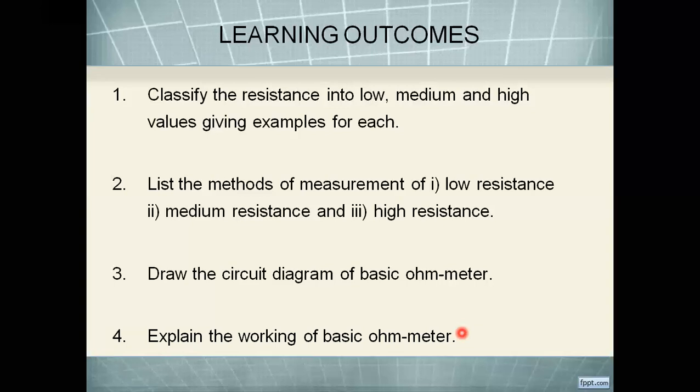We don't have a special meter with different working principles used here for a basic ohm meter. Let us recollect that we just used a simple permanent magnet moving coil instrument which deflects proportional to the current flowing through it, and we have that PMMC in series with some R0 resistance and in series with the unknown resistance which we want to measure. We use that simple technique, and let me go to the slide again.